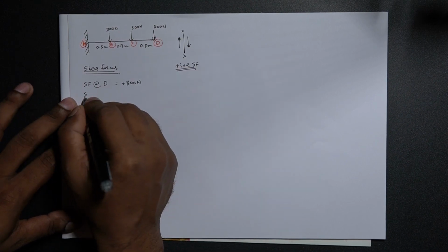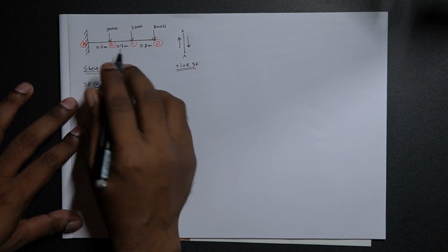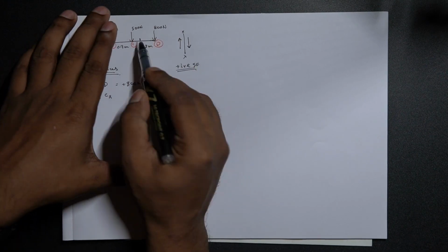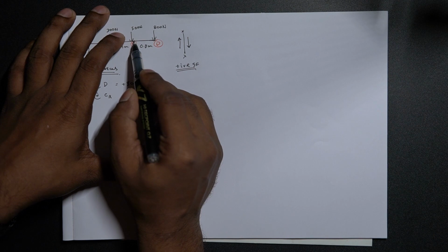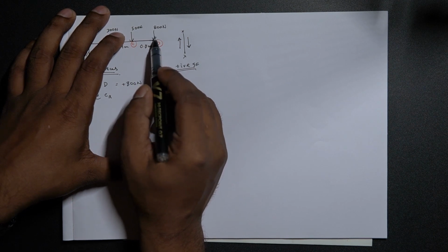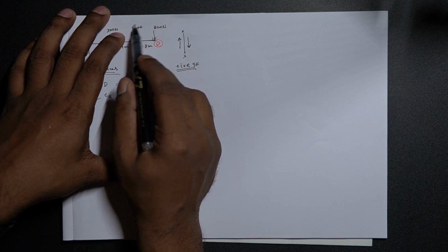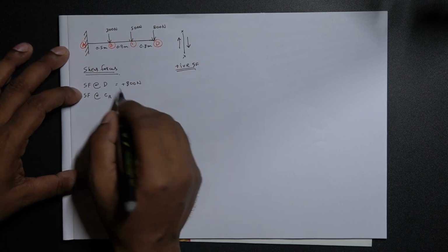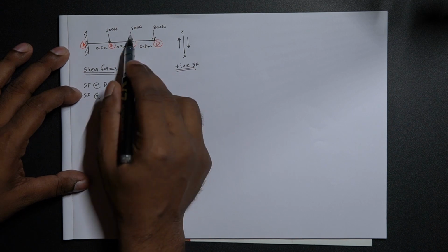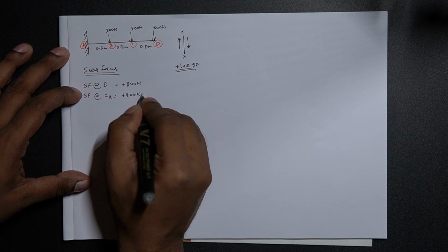Next, moving on, shear force at C, towards the right of the C. So we are going to consider the shear force just to the right of C. We are not going to include C here because we want to see the exact amount of force that has been reflected just before the incidence of another 500 newtons of force. So just towards the right of the C, we have a shear force of 800 newtons, which is going all the way across. Since it's a constant thing, it would be plus 800 newtons.